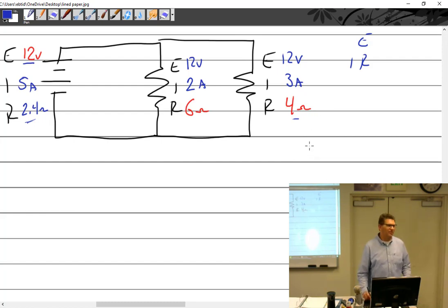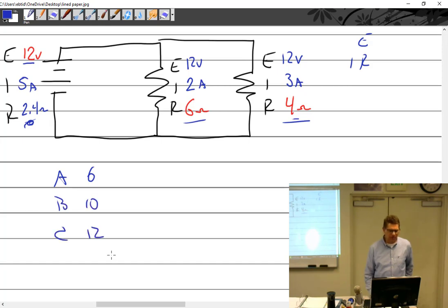So there is an FAA test question that says something like, you have a parallel circuit with a total resistance of 2.4. One resistor is a 4. What is the other one? Is it A, 6, B, 10, or C, 12? So you just put in every one and see which one. It only takes you 3 tries. So it's this, that, nope.